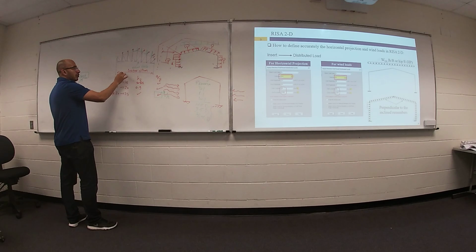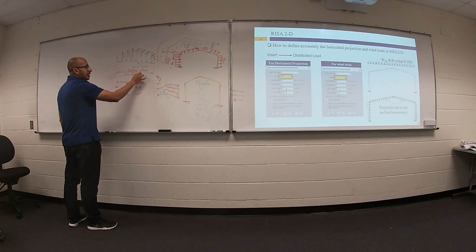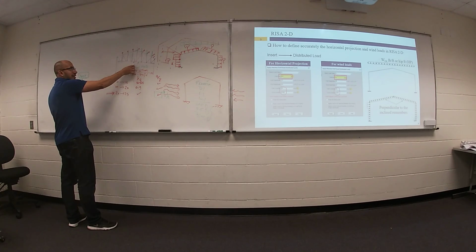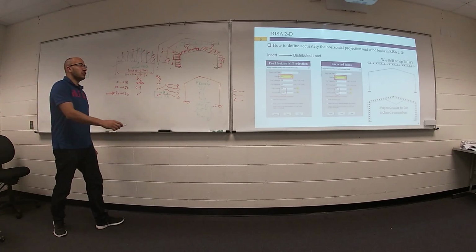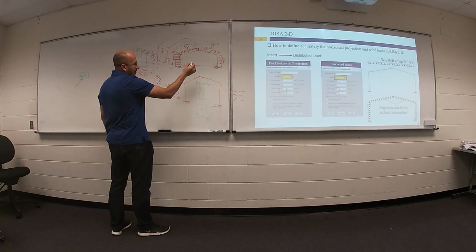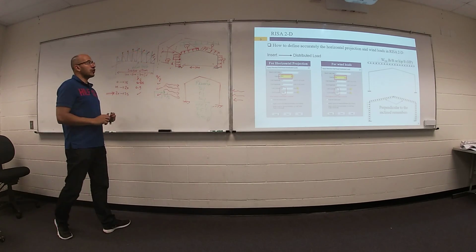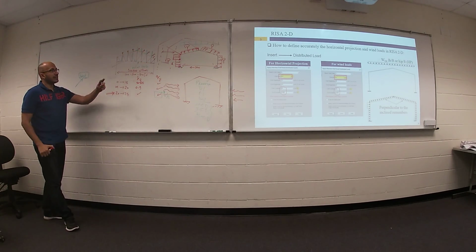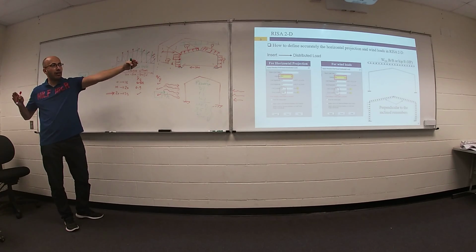If you are talking about 100 or 200 or more, 300 feet without any intermediate column, we prefer truss. If the span width of your area is 100 or below, we recommend frame. Truss is a perfect statical system for large area.